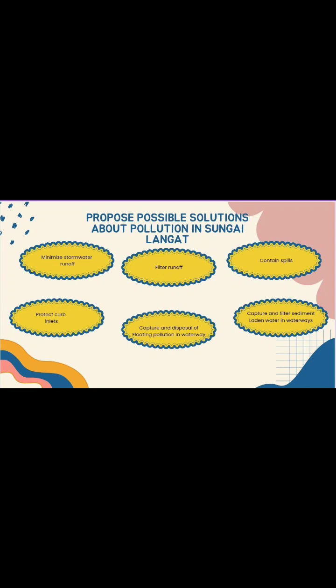In the end, a proper solution is to capture and filter sediment-laden water in waterways. Turbidity barriers are the most common solution for controlling sediment. Also known as silt curtains, they are floating barriers designed to contain the turbid water in rivers and force the sediment to settle in a contained area.